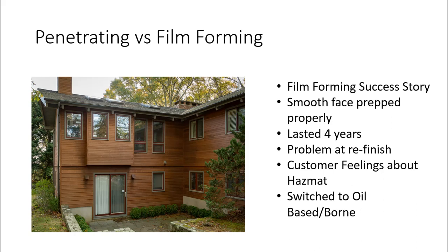Now, this customer did not like the idea of all those chemicals around his foliage and his trees and everything. I mean, he was extremely upset about the hazardous chemicals required to clean off the film forming finish, okay? So he actually went to the expense of having them clean it with the oxygen bleach, and then he had guys sand down his whole house and then did the research and put himself in an oil-based penetrating finish so he would not have to use wood strippers every time it came time to finish. So your customers' feelings about the hazardous materials needed in a film forming finish is also a big consideration.